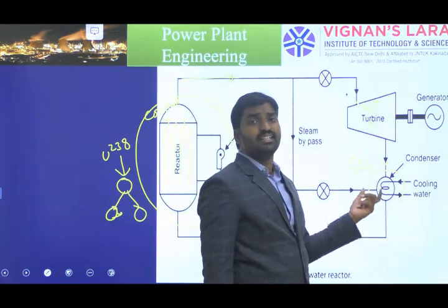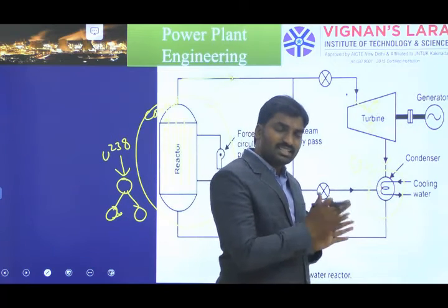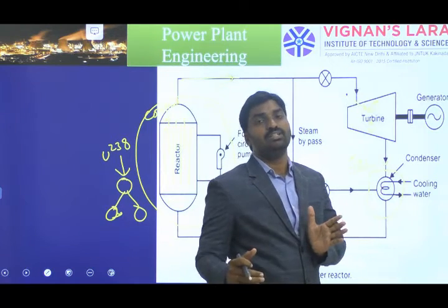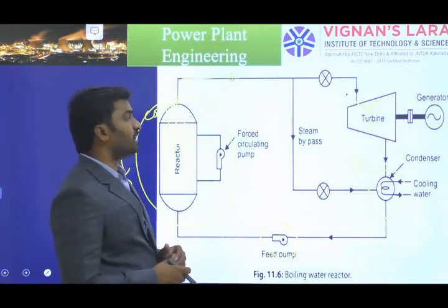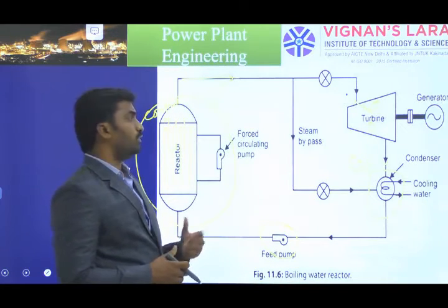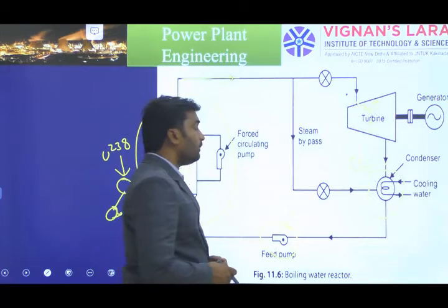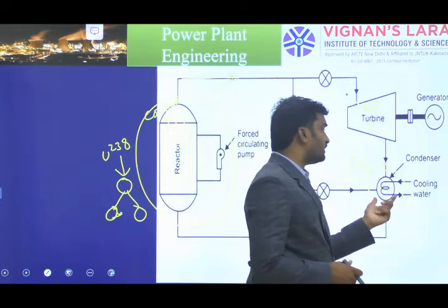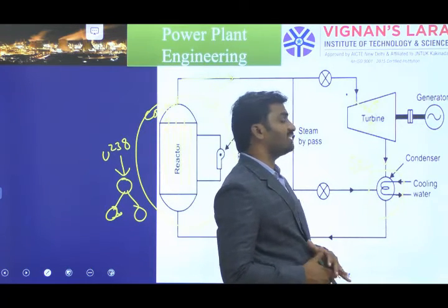So the condenser is a device. In this condenser we convert the entire steam part into the liquid format. So condensation, you already know very well. In condensation, two types of condensation are there: film condensation and drop-wise condensation. Okay. So most of the condensation takes place in the condenser and it requires the cooling water supply.